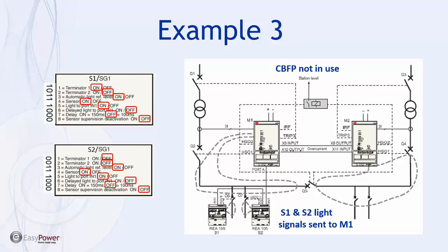So really it's just a matter of evaluating what you're comfortable with and seeing how fast your overcurrent protection is operating, how much incident energy is added due to the breaker delay, and then obviously the more conservative approach would be the fast parallel tripping.